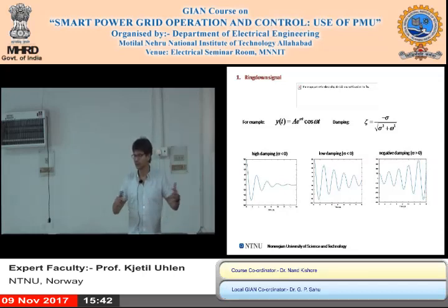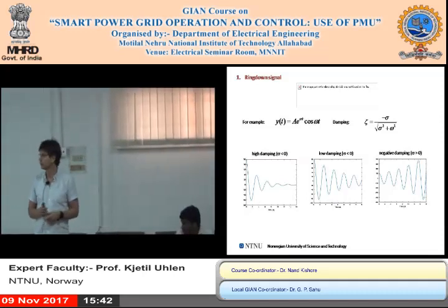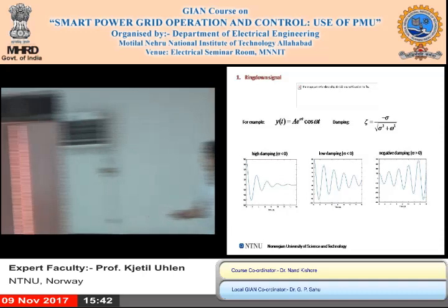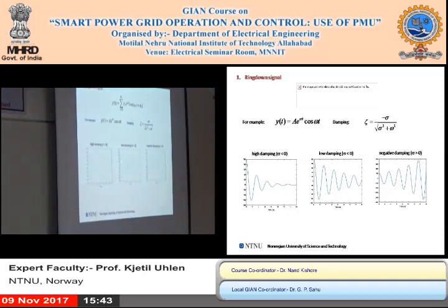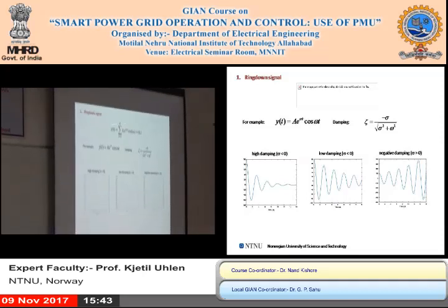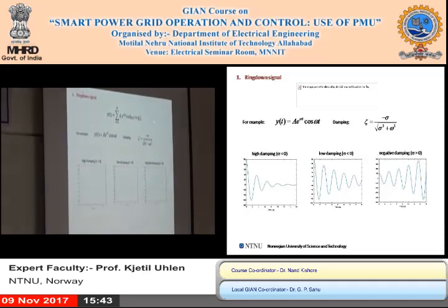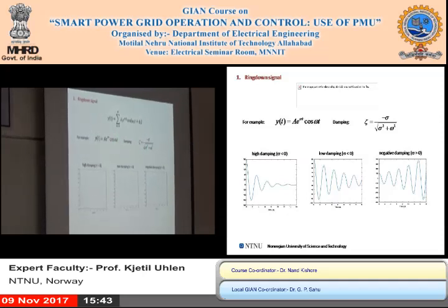If you don't have access to a power system simulator and the ability to do modal or eigenvalue analysis, you could simulate the disturbance and track the ring down of the disturbance, and based on the ring down you could identify parameters of an exponentially damped sinusoidal signal and compute the frequency and damping of that signal.